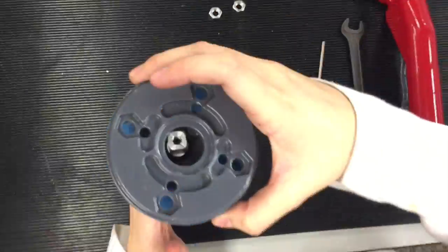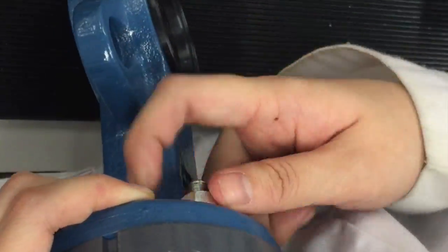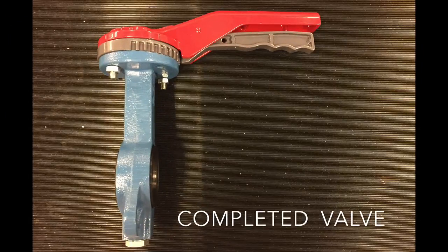Next, secure the ratchet disc onto the valve body using 2 hexagon screws and hexagon nuts arranged diagonally to each other. Finally, attach the handle and lever to the valve body with some gentle taps. This is how a completed valve looks.